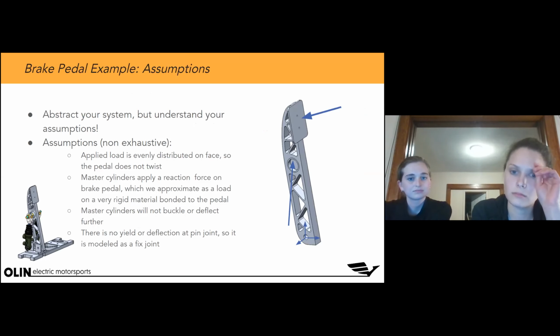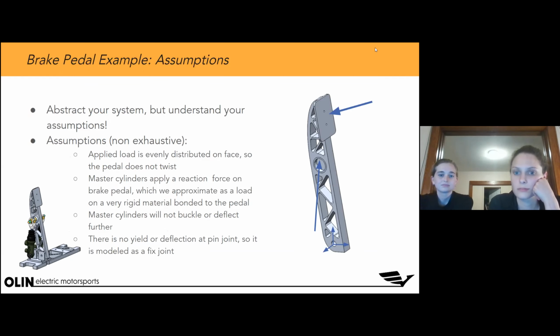One quick thing, two things actually. If you're running really simple analysis on a ruler and you push on both ends, ANSYS is just going to squish that ruler into a little block. But in real life, if you push on either end of the ruler, it's going to bend out of plane, like a piece of spaghetti that bends and breaks. That's called buckling. A static analysis in ANSYS won't let something bend out of plane, because it assumes everything's perfectly in plane, perfectly linear. So that's something to keep in mind.